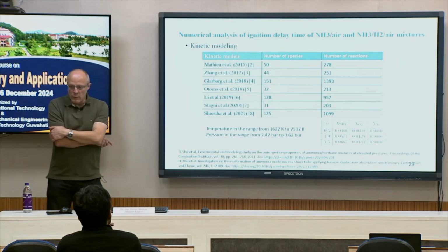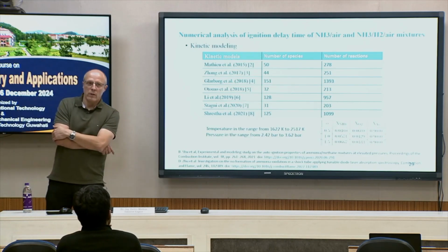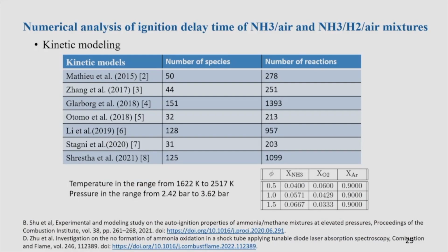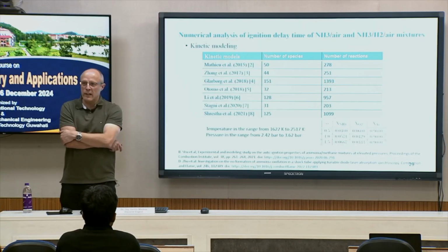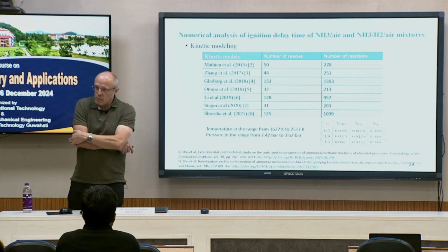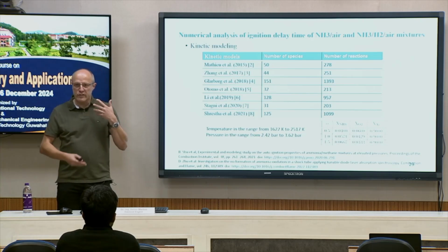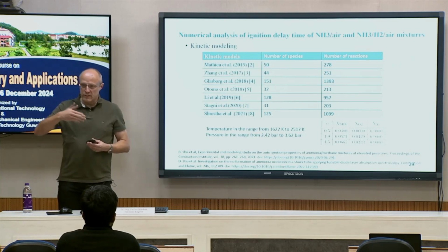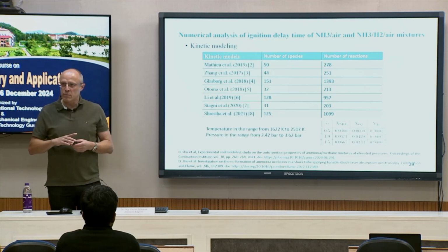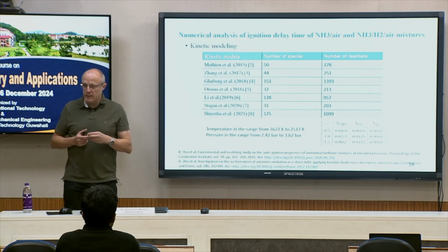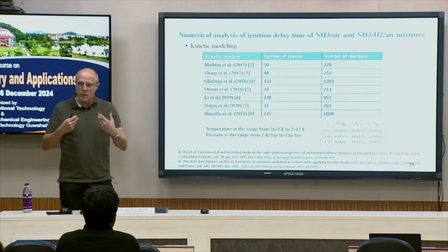So, okay, now we have talked about the example, and that's a classical way. When I start to use Cantera, I take such an example and play with it. First, I do the same calculation and check, do I get the same results? Is everything working properly? And then, for example, I change the temperature, I change the pressure. So what is the influence? And if I'm confident then with my simulation setup, I use it for specific topics I'm interested in.